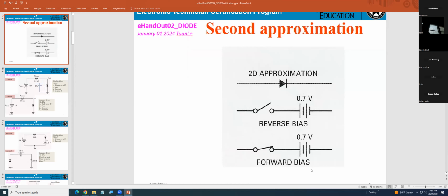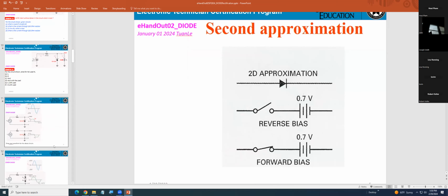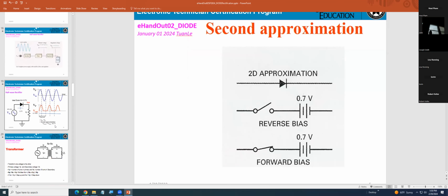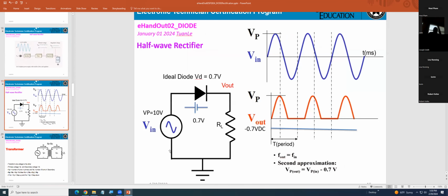If they reverse bias, that means they are off, okay? Then basically you see that they are open. That means no current can be flowing. That's the only thing they want. So if no current is flowing, that reverse bias one is the same as zero, right? Right. Okay, now, this is the only thing I expect when you see the circuitry.